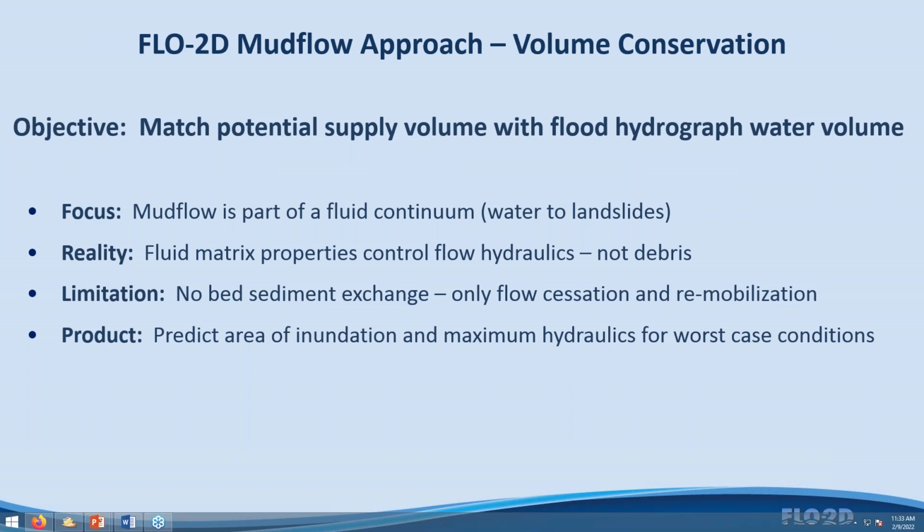The limitation of the model with mud flows is that there's no exchange with the bed sediment. That is, the mud flow can flow and then cease flowing and then remobilize, and it's tracking the sediment by grid element in terms of both the sediment and the water. So it calculates the concentration on the fly for every computational time step.